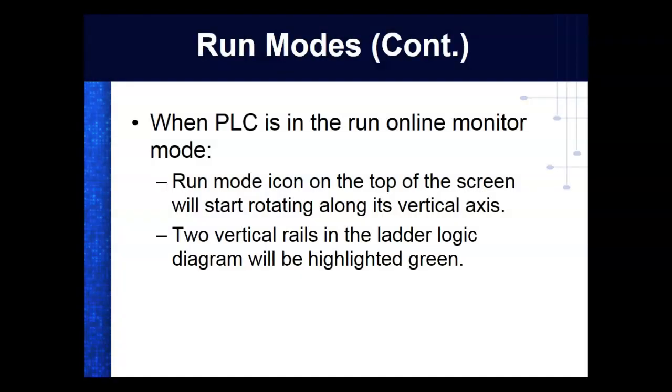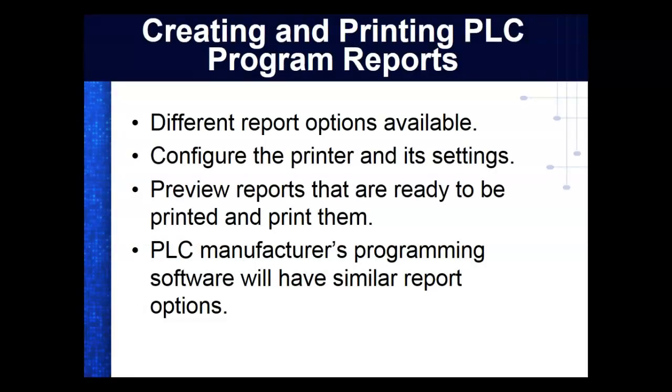Run mode, and the PLC is in run mode, online monitor. So we can be in the run mode without having the PLC hooked up. Everybody understand that? So once you switch that server to the run mode, it's going to do what? It's going to run the program, whether the computer's hooked up to it or not. It's just that if we switch to the online mode, we can monitor our contacts, which is a great troubleshooting tool, guys. I mean, it is unbelievable how much that's helped us.